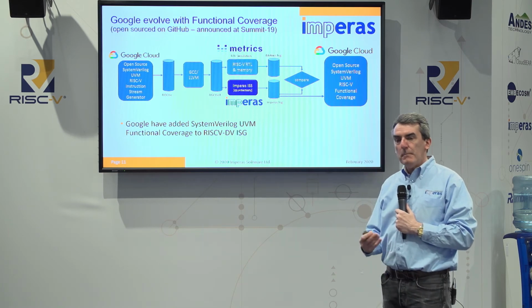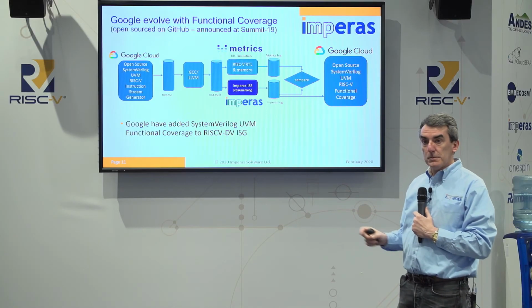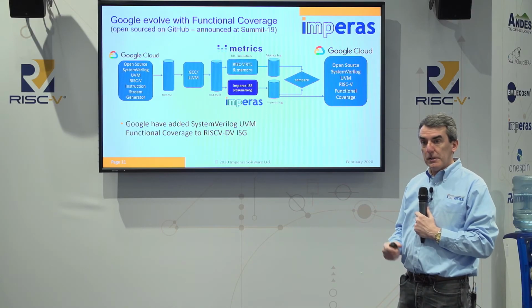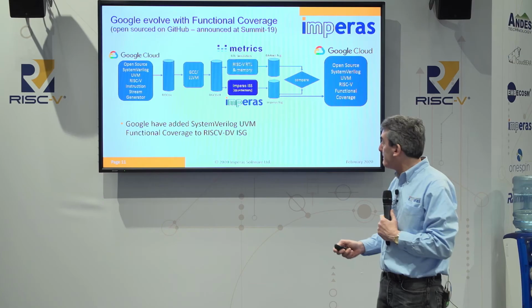A processor has many complex states, and it loves to take interrupts and exceptions. So while you might have a pure stream of instructions on one side, as they run through the processor in real time, you take an exception, you may stop the functional trend that you were expecting. So your coverage needs to come at the end of what you actually saw. That's how you know how test is complete.